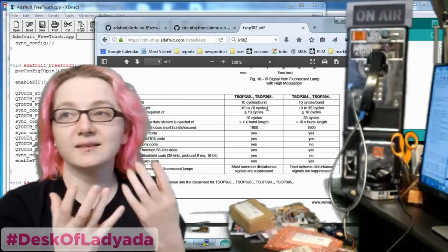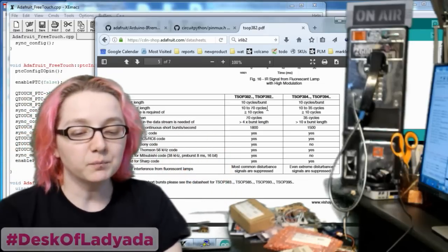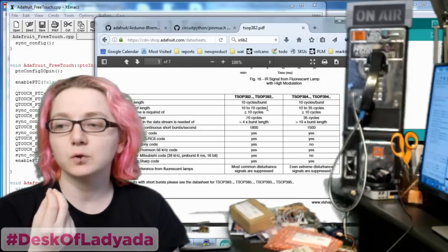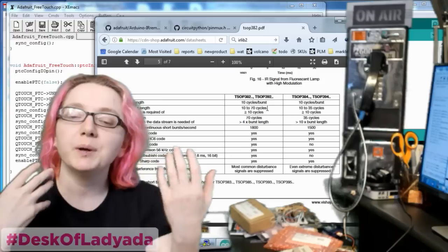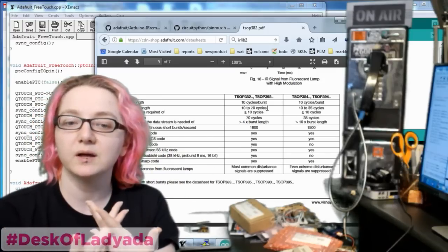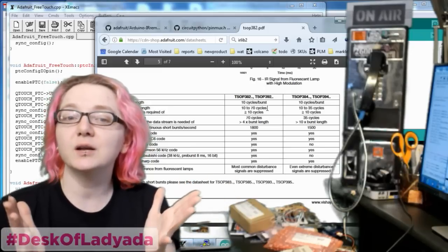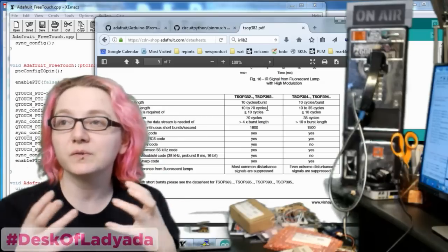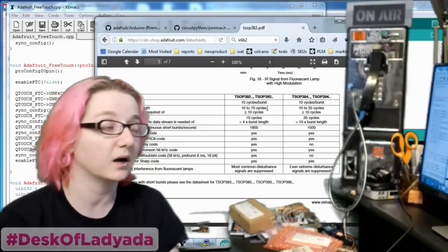What really matters is how many bursts it can handle, because some remotes have really long data strings, and some have really short ones. If you're pairing this with a device that's going to be used with a remote that has really long codes, you want to get a long code receiver. And if you're using short codes, you want a short code receiver, because it'll try to do some smart filtering to make sure you don't get codes that are too short or too long, or it'll start cutting off.